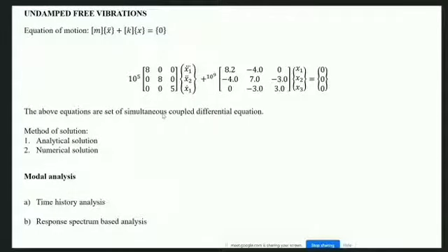So in this response spectrum analysis, it will not be that rigorous, but we will only get the design value, or otherwise speaking, the maximum value multiplied with adequate safety factors. So mostly response spectrum based analysis is practiced, and that is depicted in our code IS 1893